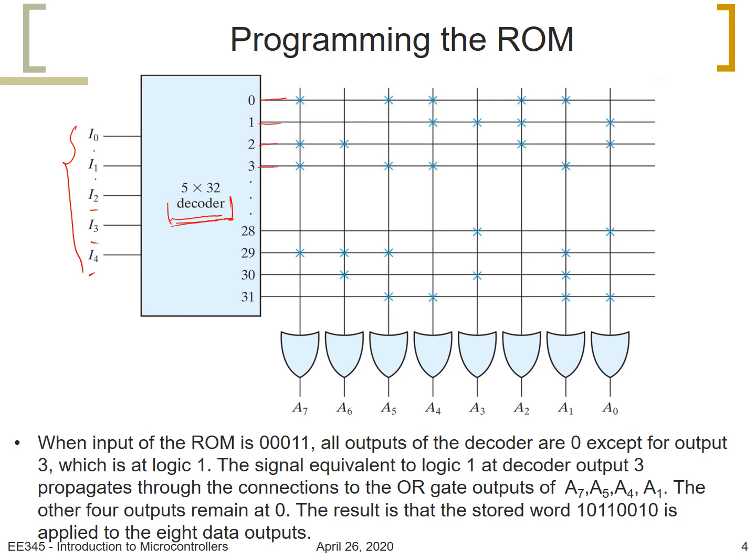And this memory is 32 words by 8 bits per word. Now, the fuses, as we have just mentioned, there is one here, so this is a temporary connection, and one here, and one here, and one here. So these fuses will remain connected, and the other fuses at the zeros will be blown.